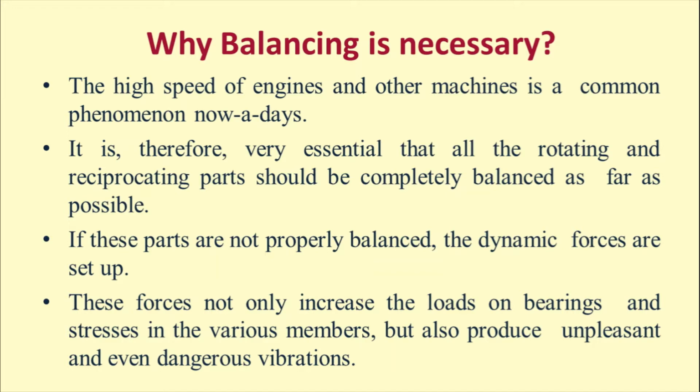If we consider the case of a connecting rod, then after proper study and observation, we must understand that one end of the connecting rod performs pure rotation, and the other end moves with a simple linear reciprocating action.